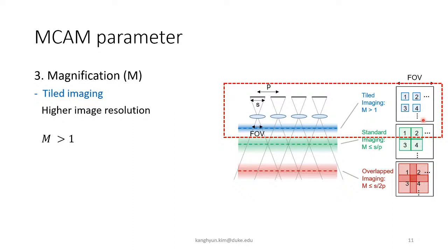In this type of tiled imaging configuration, another benefit of the MCAM becomes imaging throughput. Compared to a standard step and repeat imaging with a standard microscope, an array with n microcameras can image a specified surface n times faster, since it has to scan n fewer locations. A second benefit is that of greatly reduced requirements of the motor's travel range, as it only requires to move a distance of intercamera spacing to fill the gap.